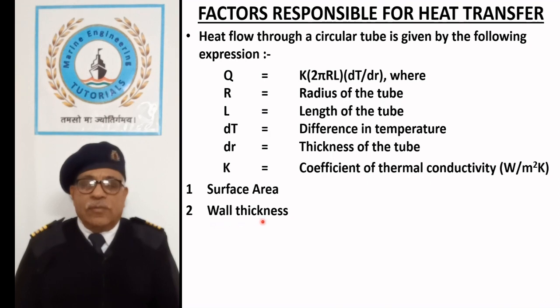Wall thickness. Lesser wall thickness improves the heat transfer, but it increases the stress, which may cause rupture of the tube. Reduction of the tube diameter reduces the stresses acting on the tube wall. Thus, for keeping the stress within limits, tube thickness can be reduced, although tube diameter below 10 mm is not suitable.